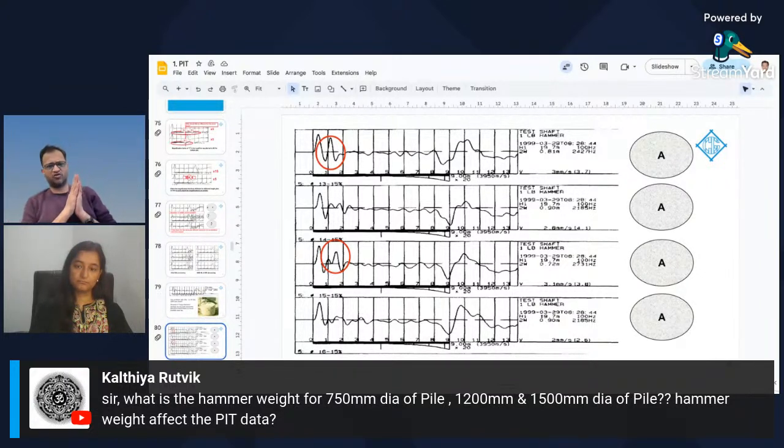Regarding your hammer weight, I typically like to use different sizes of hammers. First of all, hammer weight is not that critical, but you use a 3 pound hammer, a 7 pound hammer. I usually take a bunch of hammers to site, right? The reason is that the large or heavy hammers will be able to impact the pile harder, so the waves can travel. If I have a long pile with a large L by D ratio, I will typically use a large hammer first because then the wave will be able to go all the way down to the pile bottom and reflect back up. So it will carry more data up to deeper depth, right?